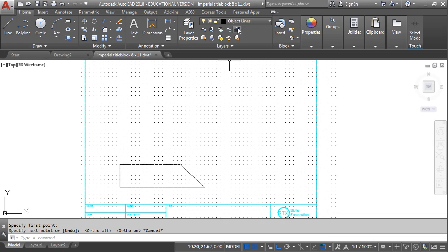All right, so instead of object lines now, I'm going to go construction lines. So I'm going to click construction lines, I'm going to go line, and I'm just going to create a bunch of lines right now in yellow. Hit escape, hit spacebar. These are all the actual points that I'm going to use to create my next objects. I keep hitting spacebar here, I'm going to come across here, and across here, spacebar. Again, it doesn't really matter where they are right now, because you're going to change stuff there.